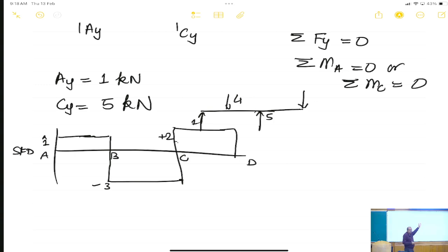this is the, can everybody see the shear force diagram? You should be able to, at least for cases like this, draw the shear force diagram directly. I have just followed the rules, going through the details. Starting from A, there was a force of 1 kilonewton. So, on all sections to its right, we will have plus 1.